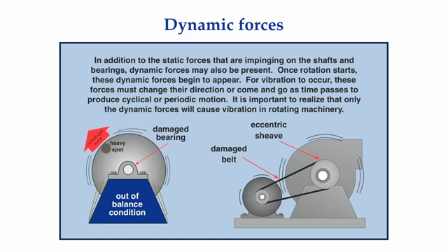Other problems that can cause dynamic forces are eccentric sheaves, damaged bearings, damaged belts, or improper meshing of gears, to name a few. What is vitally important to understand is the only types of forces that can cause vibration are dynamic forces.